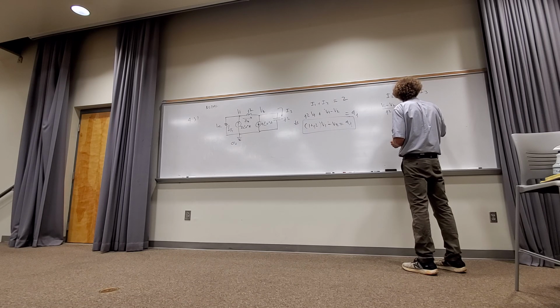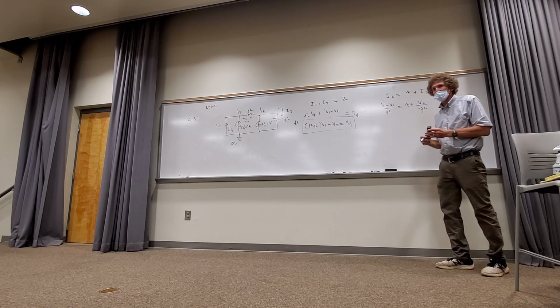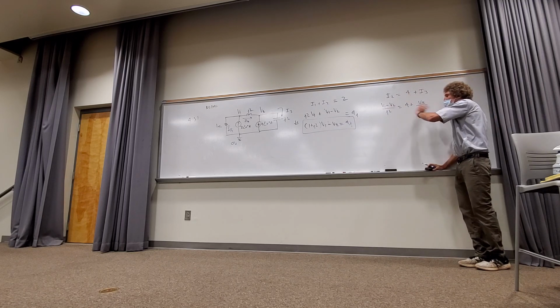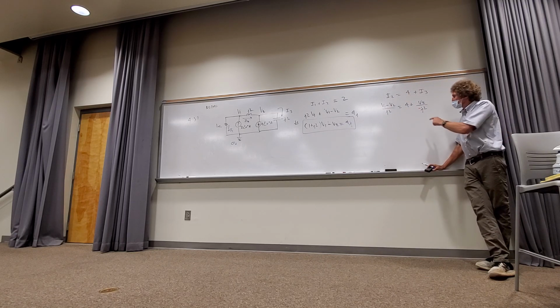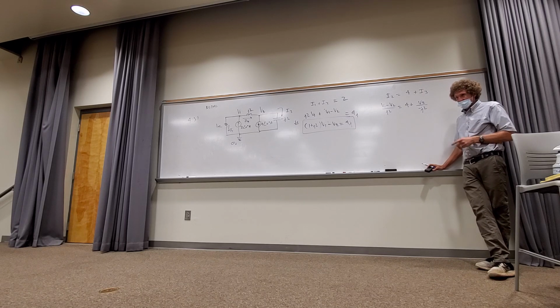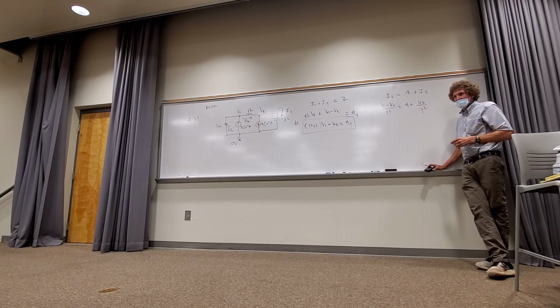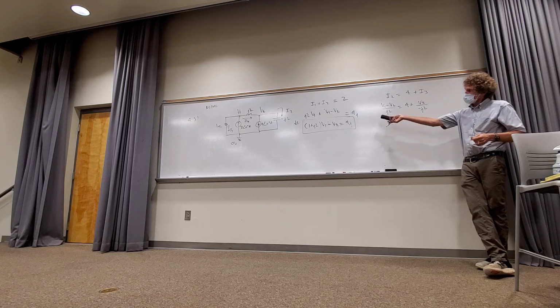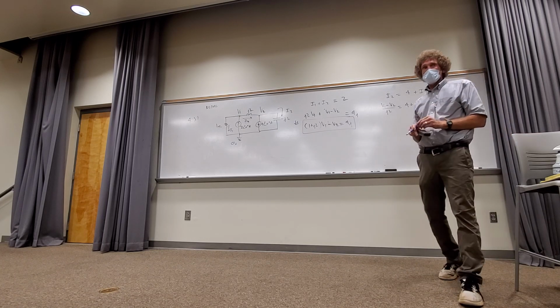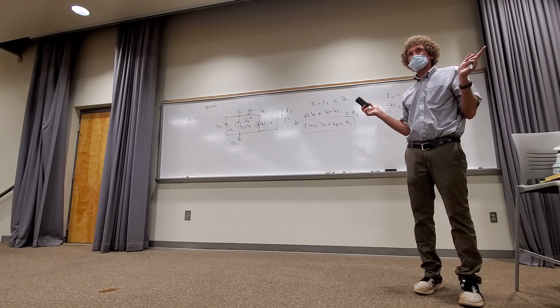Divided by minus J2. Now there's another class coming in, but here's what I would do. Multiply everything by J2. There's going to be a minus sign that appears in this one. It'll be a minus V2. And then organize it just the way I did over there and solve it. Now you're going to get a 2 by 2 matrix. You with me, class? Set it up and solve it.